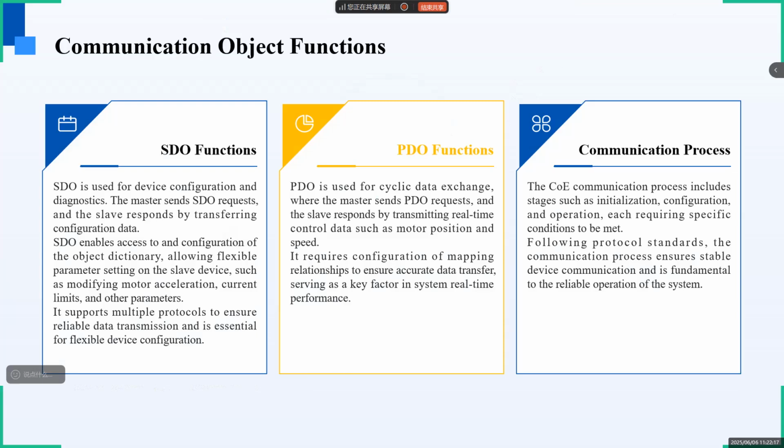SDO is typically used for device configuration and diagnostics. The main station sends a single command. The substation returns specific data. Using SDO for object dictionary access and configuration allows flexible parameter configuration.